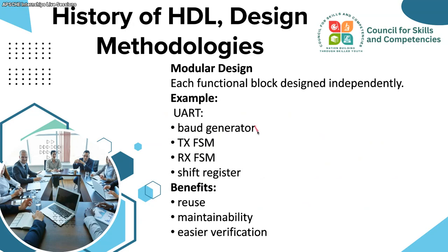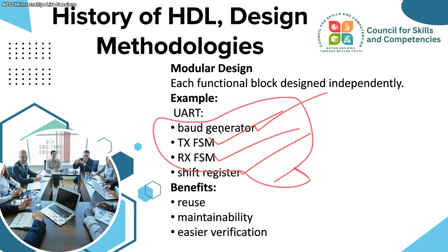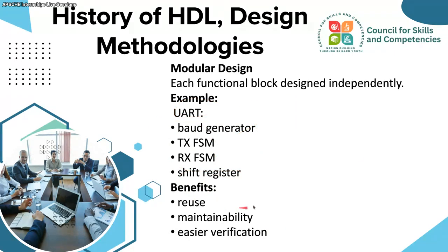So this can be designed independently, this independently, and we can club it together to become one UART. That is what I'm trying to tell. And if you want to do it for another system, you can reuse it and maintain it easily, because it is in small blocks, you can go and reuse it, and it is easier for verification. Okay, so these all are some advantages when we use this modular design.